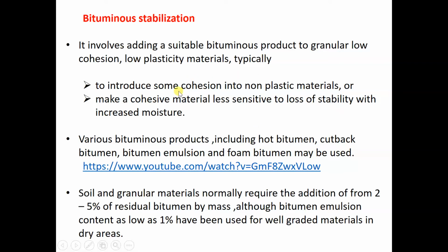So for bituminous stabilization, the objective is to introduce some cohesion into the non-plastic materials, a bit like cement as well, to make the material less sensitive to loss of stability with increased moisture.